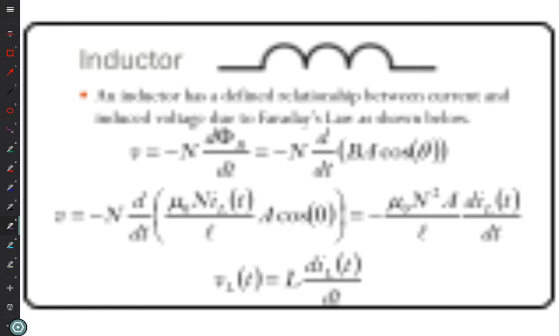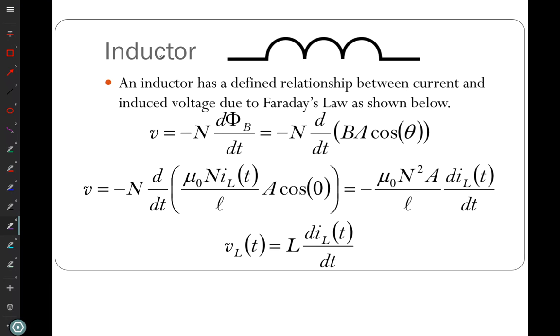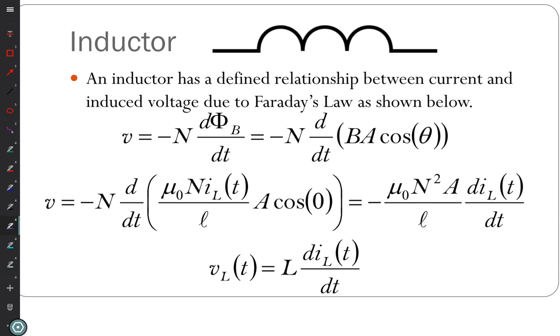What about inductors? In the inductors, you see I have a lot more preparatory work here. For the inductor, Faraday's law of induction has a minus, and what does the minus sign mean in that equation? That's the EMF opposing the motion. Yeah, it tells us that we have to look at Lenz's law, because our induced voltage creates a current opposing the change in flux. That's what you're saying, right?